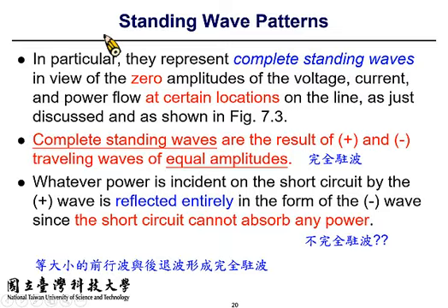However, if the V minus component is smaller than the incident wave, then you will not have a complete standing wave. You will have a partial standing wave. So the signals reside on the transmission line; some are reflected back and some go into the load. So that's what shall be the more general case. All right?